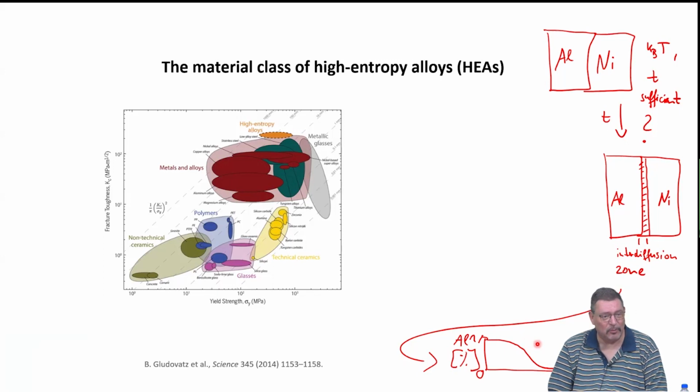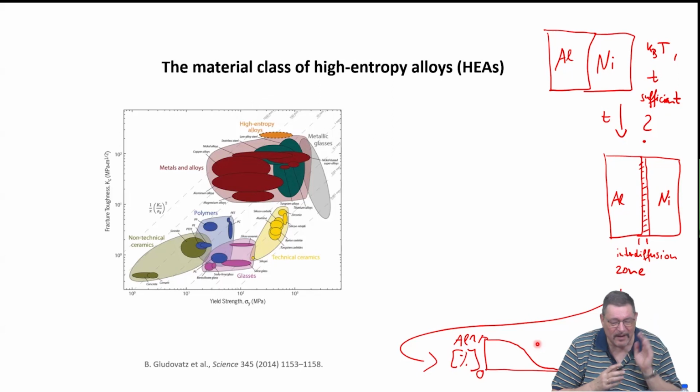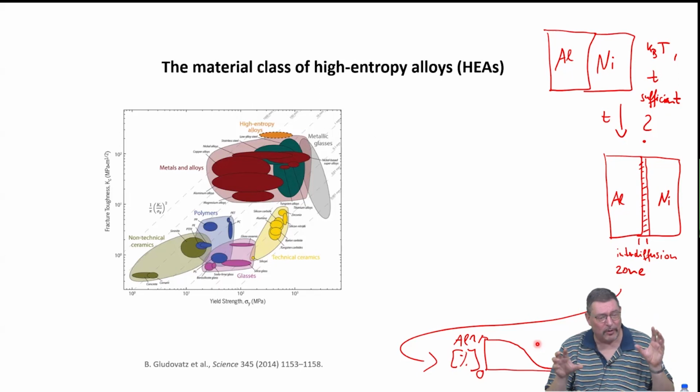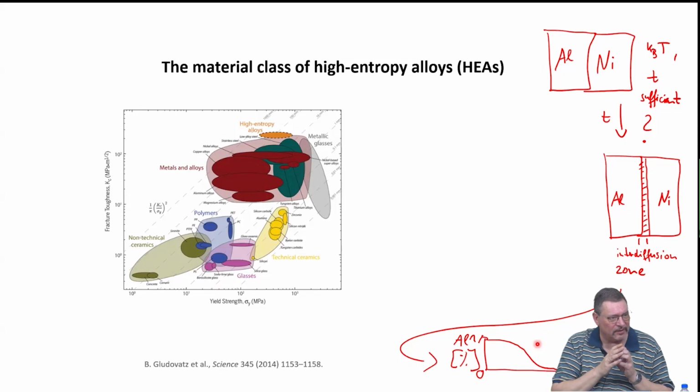And aluminum and nickel, have they different size, or are they having comparable size? Different sizes, yes. So could it be interstitial or... we can observe the correlation, but for this system, it's really that the sizes are not sufficiently different, which means that if you put an aluminum atom in the interstitial lattice of the nickel, the strain would be too large.